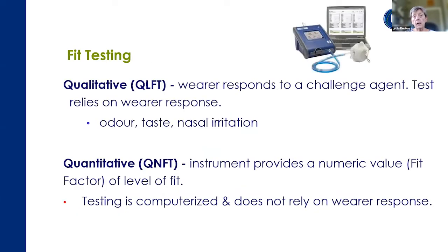Specifically, there's qualitative (QLFT) and quantitative (QNFT) types of fit testing. These are really well explained in the CSA standard Z94.4 that Simon referred to. But there is a big difference, and there are advantages and disadvantages to both. First of all, qualitative is less expensive. Well, it's not necessarily quicker to do, but it's cheaper, and instrumentation is usually just a challenge agent and possibly a hood. But it does rely on wearer response to an odor, to a taste, to nasal irritation.